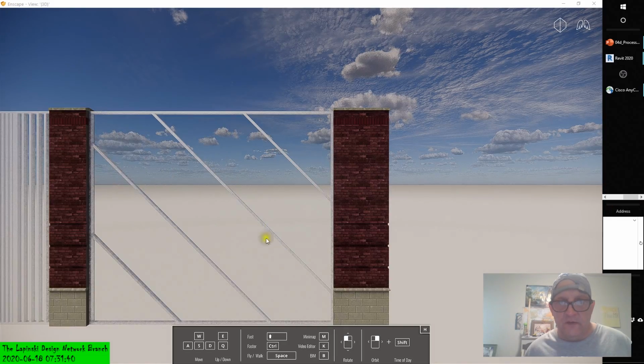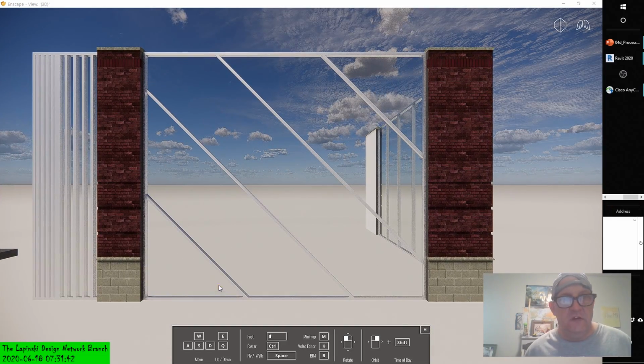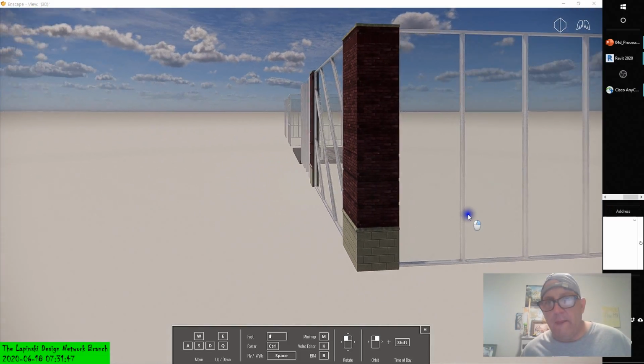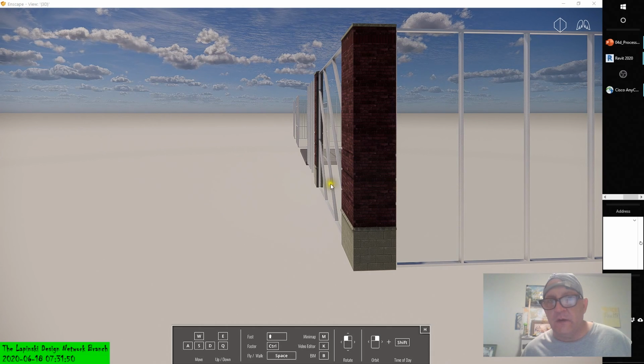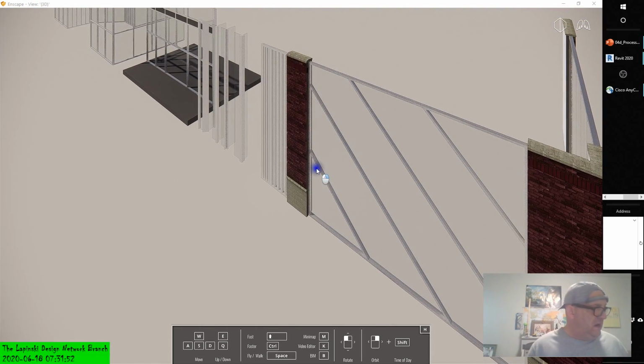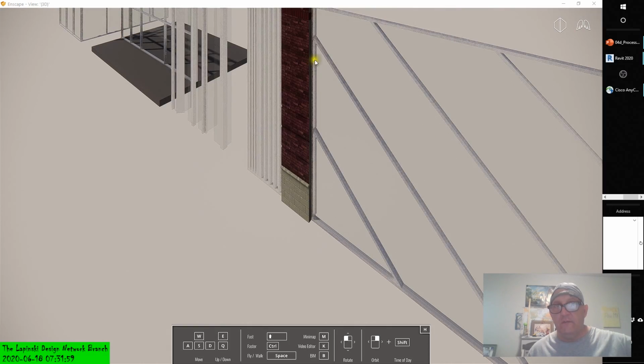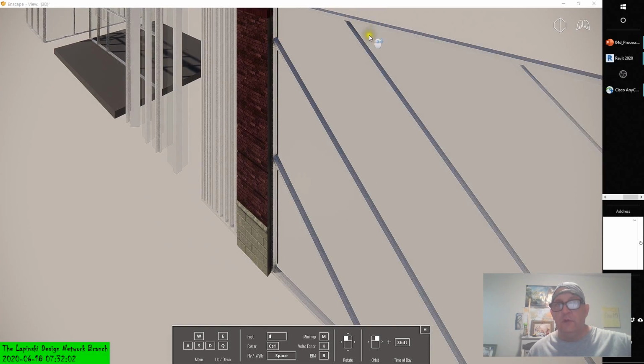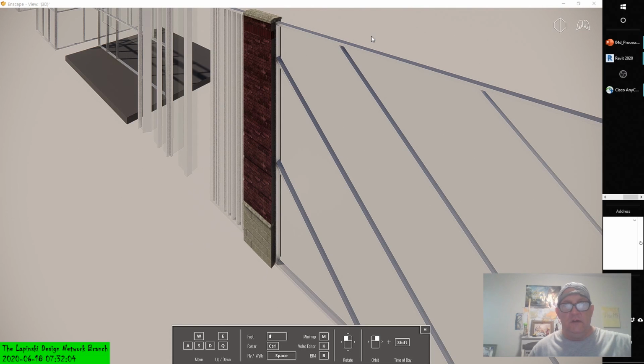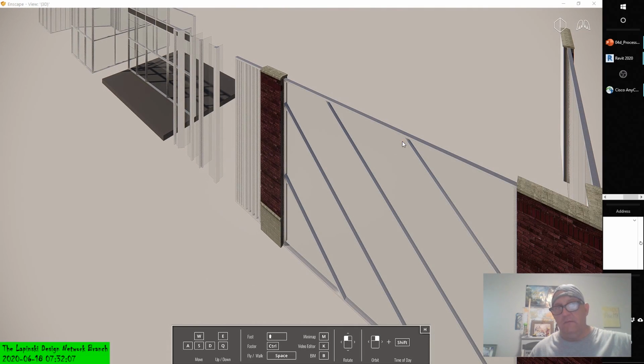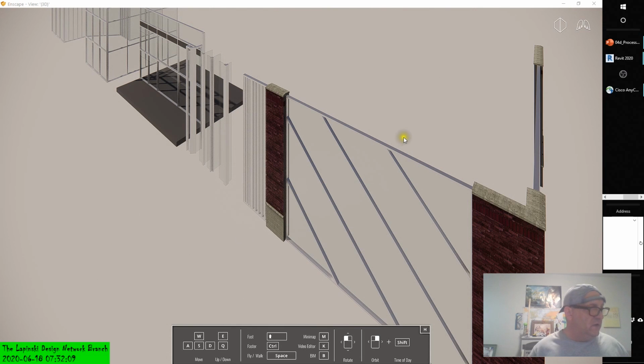So if you look at it rendered in the rendering engine, we have a stacked wall. Right? We have a stacked wall. And we created a curtain wall pattern between. And we didn't set any of the join conditions, but we did automatically embed the curtain wall system to include horizontal and vertical mullions. Now, the vertical mullions are equally spaced because the grid pattern layout was already set, which we can manipulate.